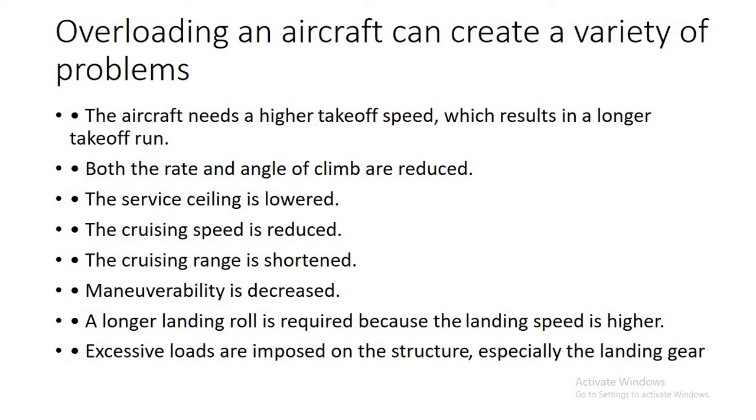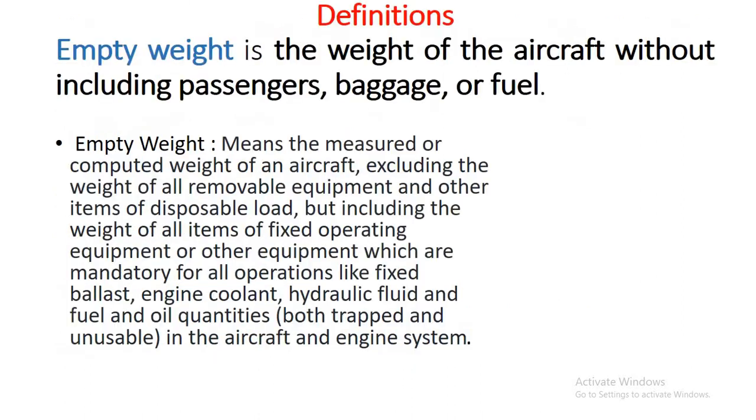That is actually very bad for the aircraft structure. Sometimes it can cause a lot of problems like breaking of structural parts, too much stress that can actually aggravate fatigue condition. So all this should be taken care of. These are the reasons why we avoid overloading of aircraft by weighing the aircraft and determining its weight at a particular time interval. Now let's see some definitions that come most often with weighing of aircraft.